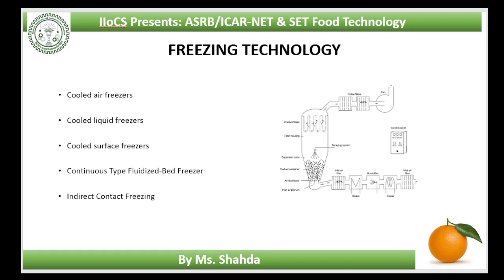Advantages of this type of equipment include good economy and space utilization, relatively low operating costs compared with other methods, little dehydration of the product and therefore minimum defrosting of the condensers, and high rates of heat transfer. The main disadvantages are the relatively high capital cost and the restriction of the shape of the foods to those that are flat and relatively thin.